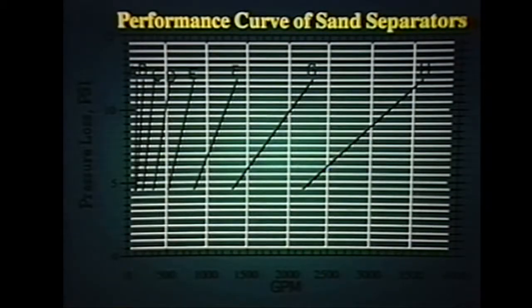There must be enough flow rate through a separator to cause sufficient swirling and centrifugal action. Generally, there must be a minimum 5 to 6 psi pressure drop across a separator. Therefore, it is difficult and often impossible to select separators to work well under a wide range of flow rates. If a flow rate changes with time, another option such as media tanks might be necessary.